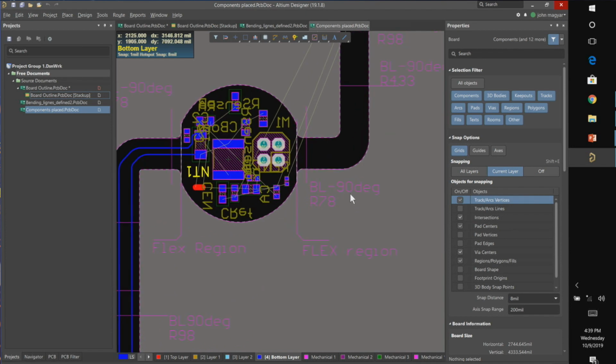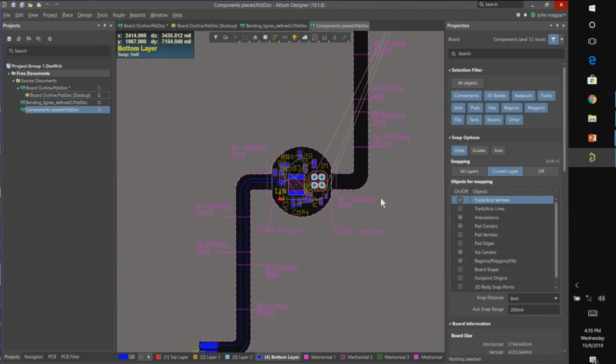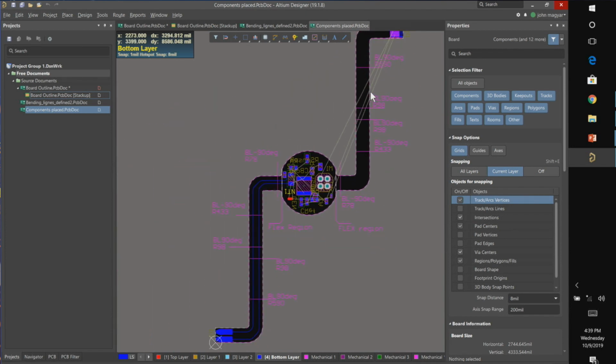And this particular design does not have anything placed on the rigid sections. You'll see in a minute, given its use, these are meant to freely move. But there are applications where you may want to put components on the flexible region. Surface mount components, of course, work best.